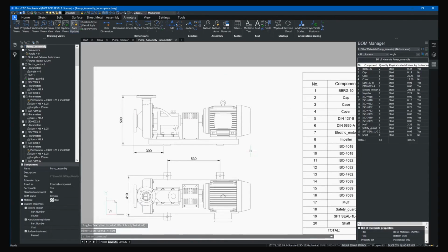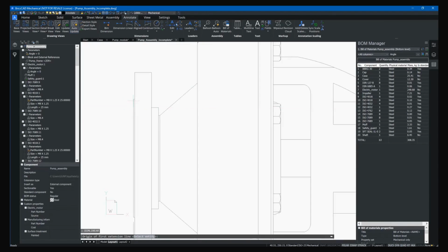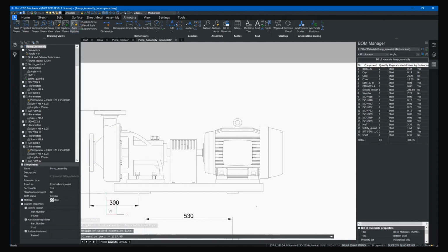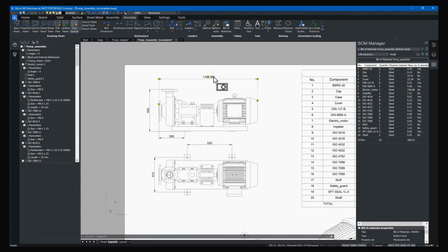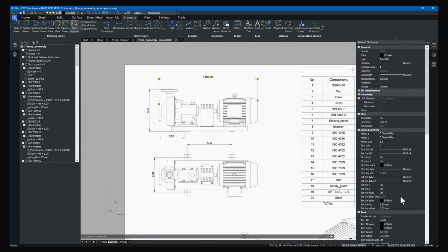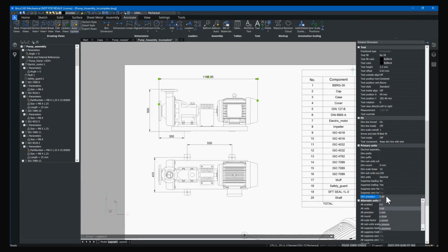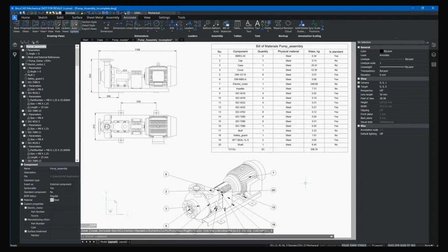Of course, if you have a part drawing, you might want to have more specific, more detailed dimensions as well, which of course is possible. And you can also place tolerances as well on these drawings. Here I will just change the value of this. This value is not that important, so I'm going to change the decimal points to a more rounded number. So here we can see a basic drawing generated from these models that we have looked at today.